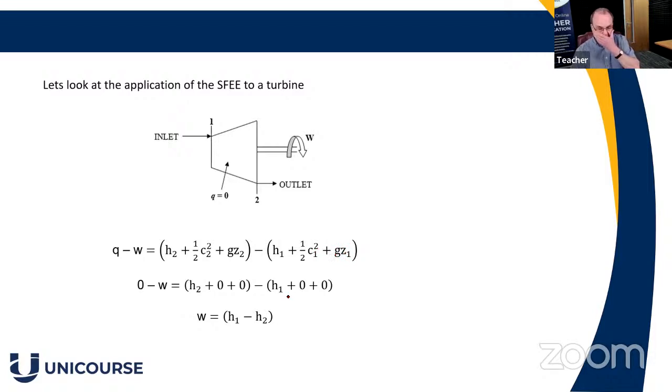The thing to note is that enthalpy is usually measured in 1,000 plus kilojoules of energy, but the velocities tend to be quite small, so there are orders of magnitude of difference. If the velocity were, say, 3 meters per second, 3 squared is 9, divided by 2, so we're talking about 4.5 joules of kinetic energy, whereas the enthalpy is usually in the order of 1,000 kilojoules. So there's a massive order of magnitude difference.